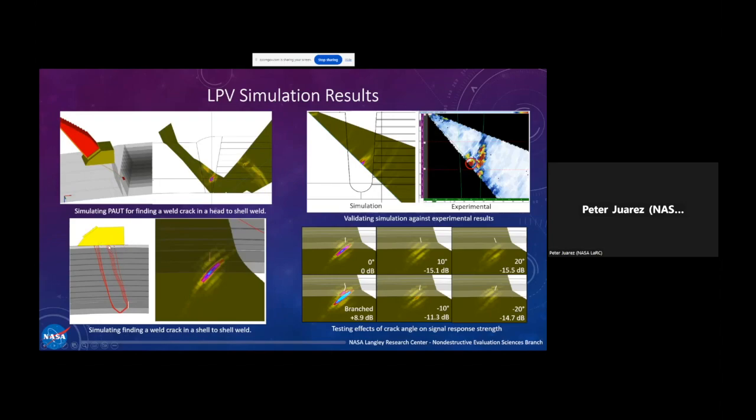In fact, if you're just looking at this, this is supposed to be a straight line of acoustic energy for the ray trace on here, and it's very, very wavy. In 3 dimensions it's actually arcing in and out of the centroid of the weld before it gets to the bottom. But then we found out that we can detect certain defects by looking at it differently.